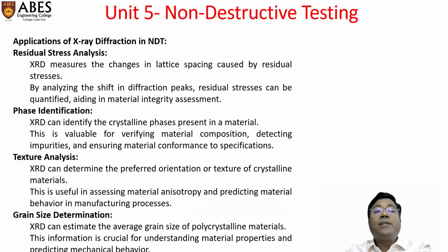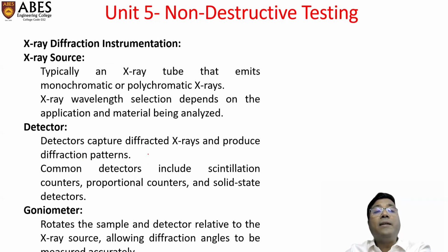So applications of X-ray diffraction in NDT: it can be used for residual stress analysis, phase identification, texture analysis, and grain size determination. All these are applications of X-ray diffraction in NDT.